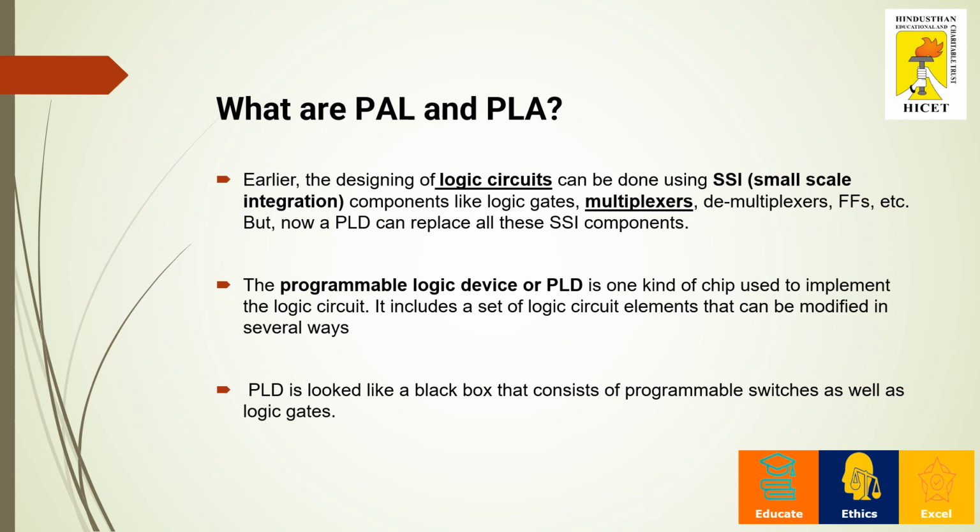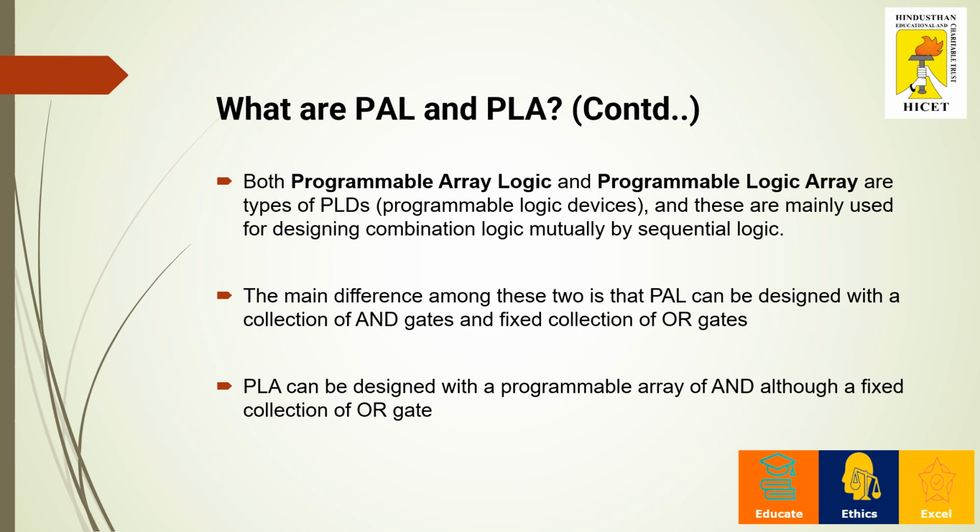A programmable logic device may be classified into many different categories. It is a kind of chip which is used to implement your logic circuit. It includes a set of logic circuit elements which you are able to modify in several ways. A PLD consists of programmable switches as well as logic gates. Since there are many programmable switches and logic gates, you can program your own devices. Both the programmable array logic and programmable logic array are types of PLDs. What is PLD? It is a programmable logic device.